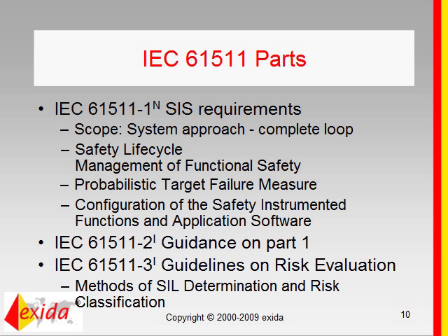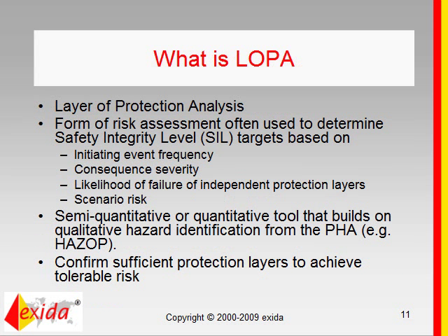need to achieve. The layer of protection analysis that we will be talking about today is also explained in this part 3 of 61511. Now keep in mind, this is informative, so anything that's stated in there is just for information. It's not required that you do it this way. There are a bunch of different ways to do SIL selection or SIL determination, but it at least gives you some idea of how to implement it.